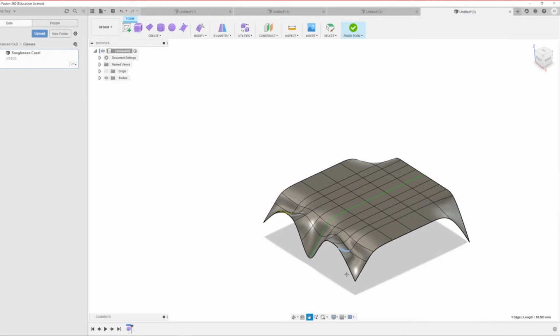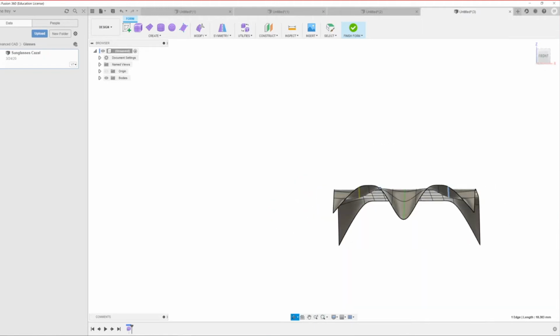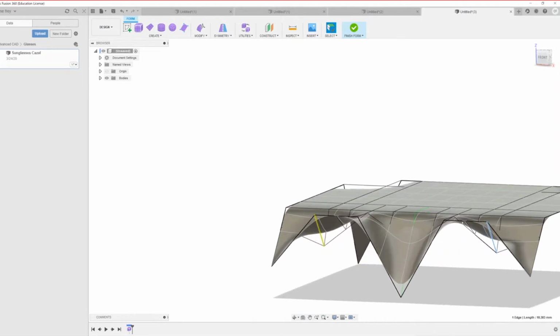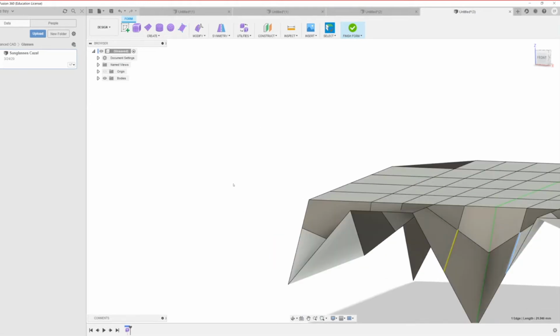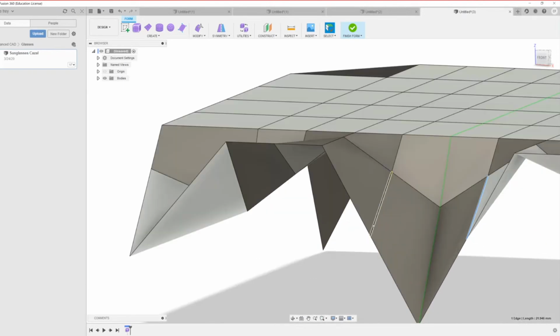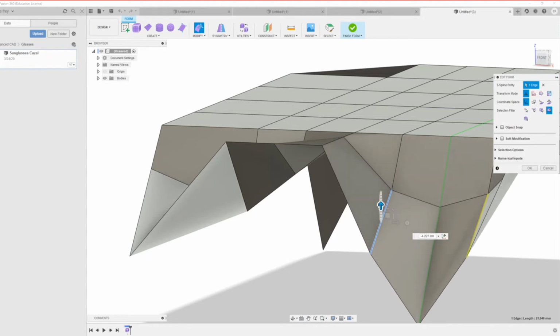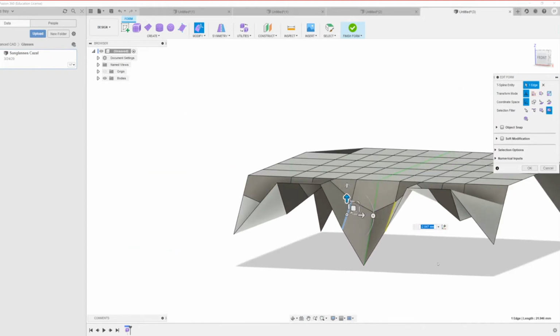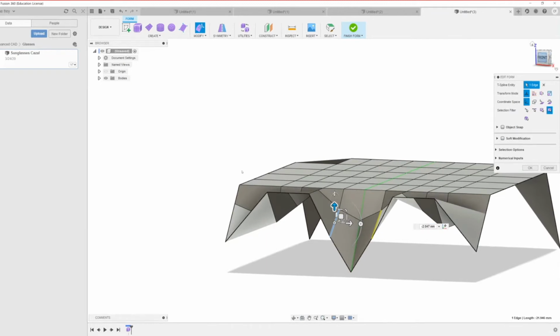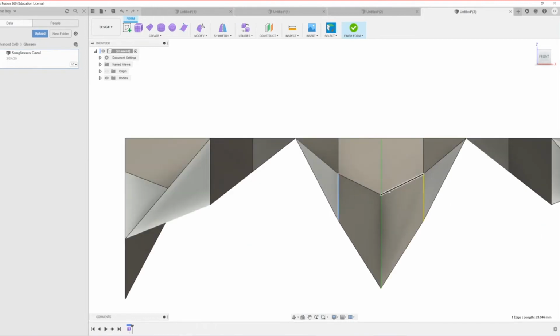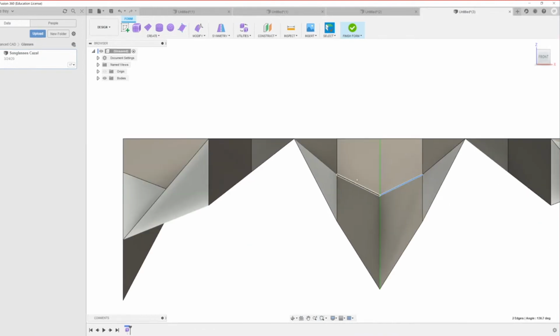But it also brings it right down nearly to where we wanted that edge as well. Actually go back into that kind of mode, and we can control that a little bit more by pulling these edges down more. So even if we were to change the actual thinking of it, we can go into there, go to edit form, and pull that a tiny bit more down in order to give it more of that scooping effect in here, which will help it more. And we can pull it down as well. So what we can do, we can pull down these faces as well, which is super easy.